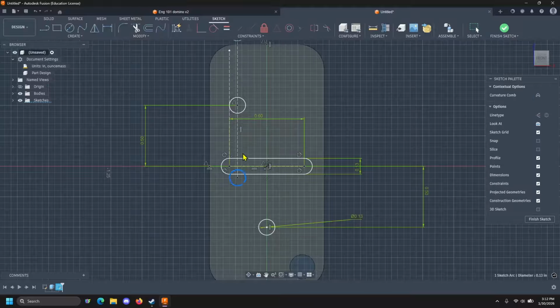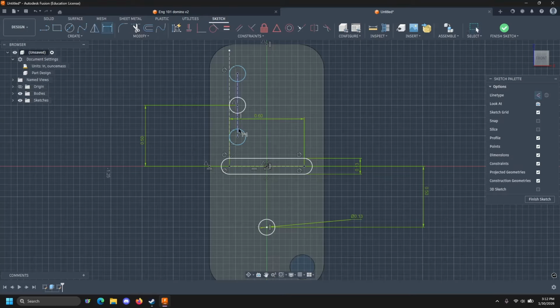The only thing now is the spacing between these, because these can still kind of move apart from each other. Now we're going to use the dimension tool again and dimension the space between two of these points. I'm going to be using 0.25. That'll give me the spacing between each of these points. So now I have 1/2 of my 6 dots. I have 3 of them, and I want to give it another 3 dots.